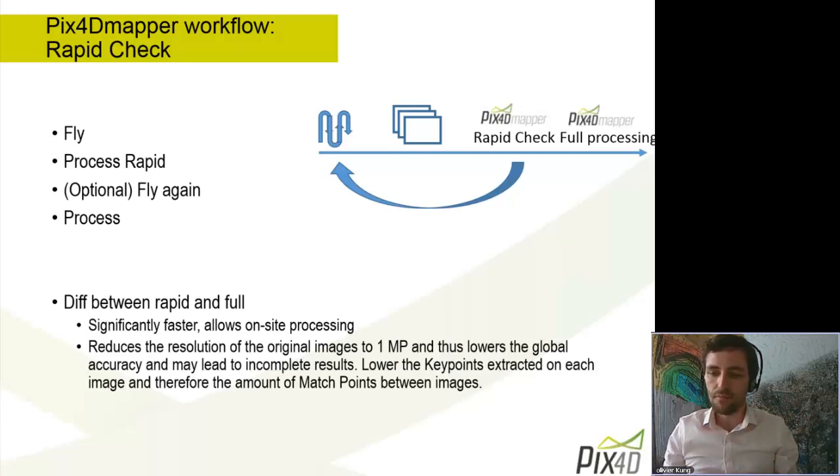When you have very low overlap, or the terrain is very complex and would require even more images, if you process the project nevertheless, it is possible, but it's much more complicated and potentially very difficult to assess correctly the accuracy of a project with a low number of images.